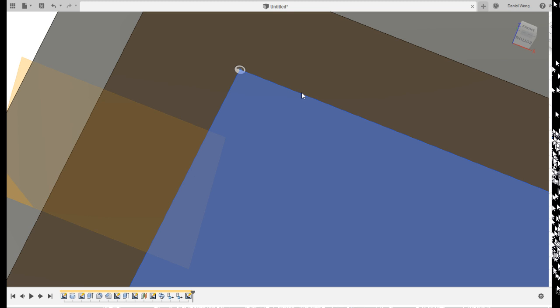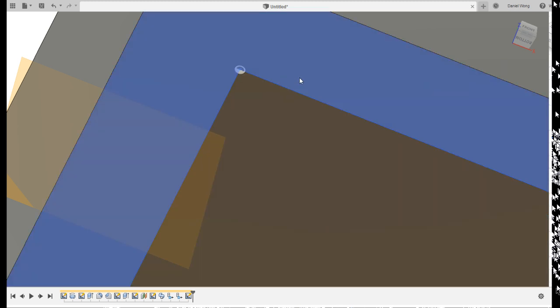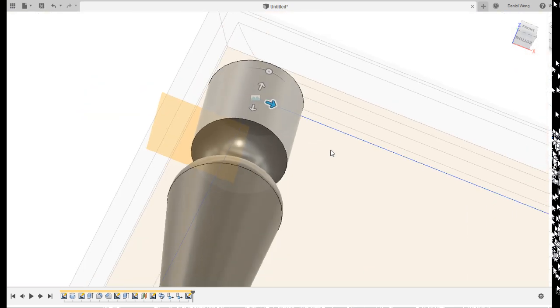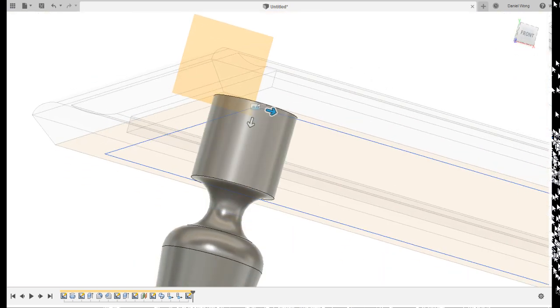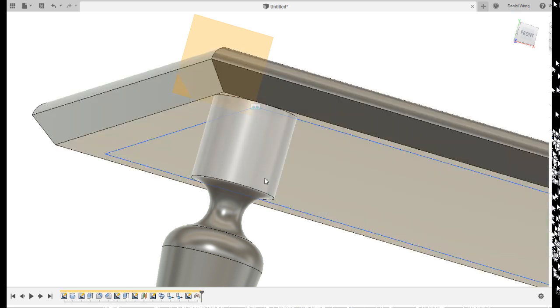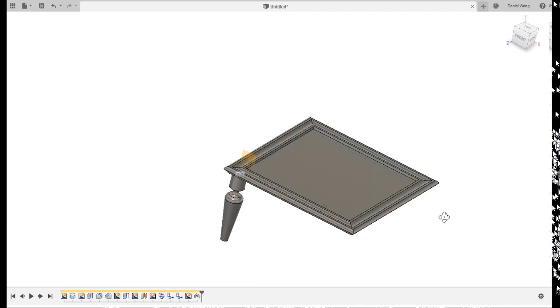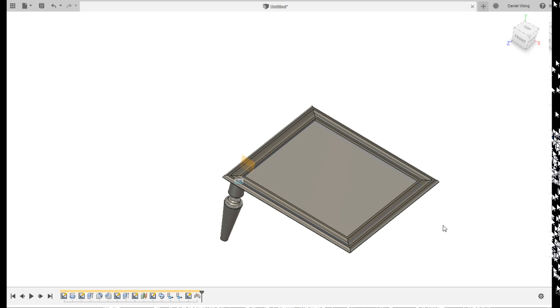Because the two joint origins must lie flat to flat, okay? Flat face, right? So make sure that when you're highlighting over, the joint origin is nice and flat on that surface, yeah? You notice that when I do that, it applies a joint like so, and then I can press OK.